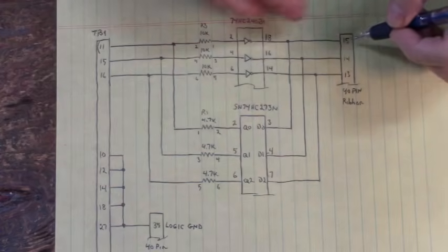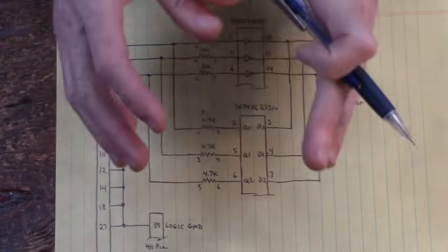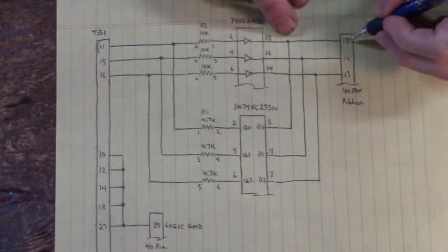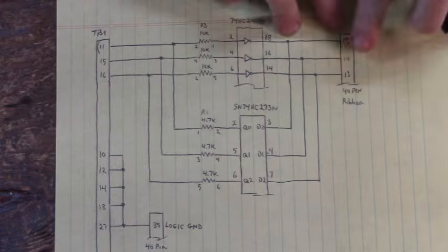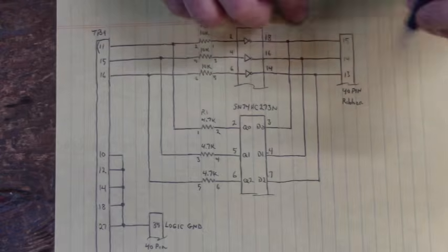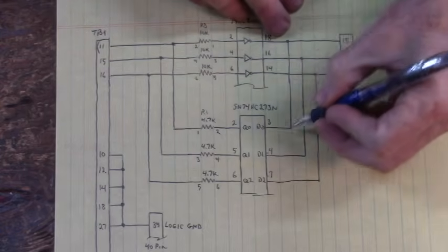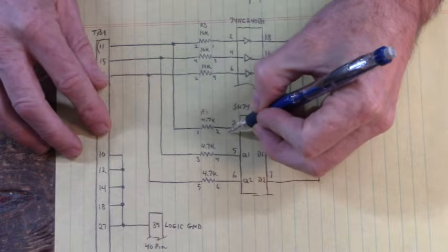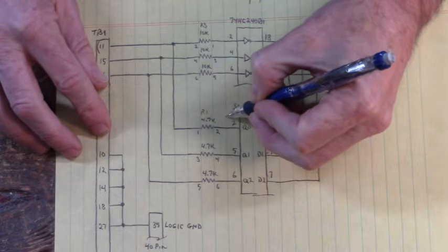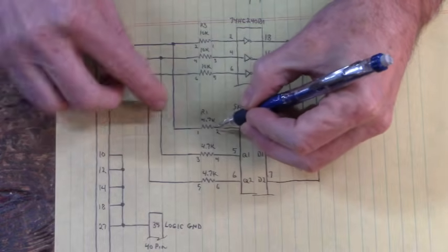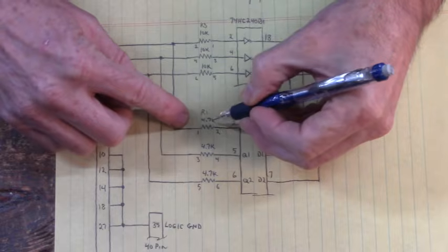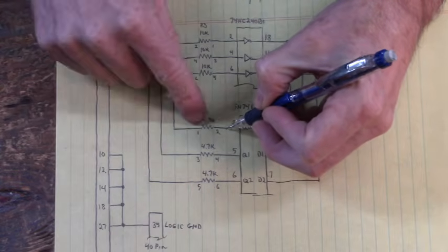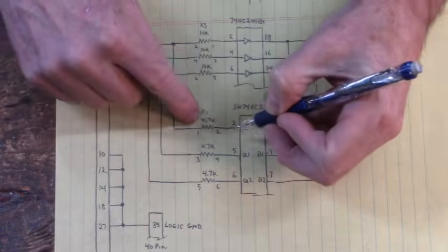When we first fire up that drive and it goes and grabs the parameters and starts setting this I/O up. If we put a high, this right here is the ribbon cable going back to the processor. If we put a high here and latch it to the output, that makes this point right here at 5 volts. And we have, in essence, a 4.7 kilo ohm resistor tied to pin 11 pulled up to 5 volts. It's a pull-up resistor.